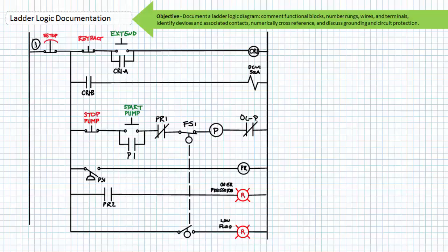First, start with wire number 1 being the left upright. Everything attached to the left upright is given wire number 1. Again, there is really only one device attached to the left upright, the left terminal of the e-stop. Method 2, however, does not skip the contents of the first rung and continues assigning wire numbers left to right until it reaches the right vertical upright.